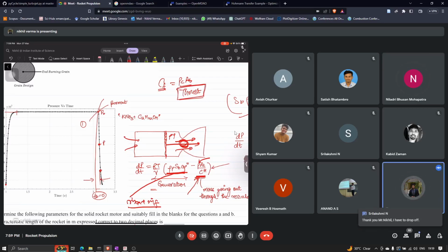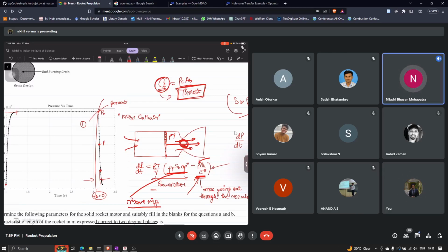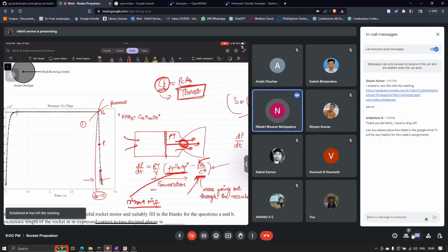How are you calculating this thrust and CF? So CF you are calculating based on this, right? Yes, CF I am calculating from that formula, 2 gamma squared divided by gamma minus 1, from that formula only. Now my PA is 101325. I am subtracting that from the PE, which is 0.2 bar. So it is giving me a negative term. And since my left side term, that is the square root term, is very low, I am getting CF negative.